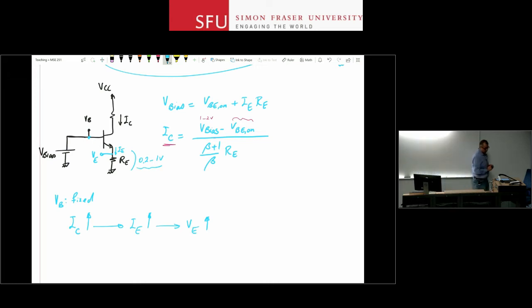Okay? With VB fixed, if VE goes up, this means that VBE has gone down. VB minus VE has gone down, right? So let me just write it this way. VB minus VE goes down because VB is fixed, VE is going up. If VBE goes down, it pushes IC down.